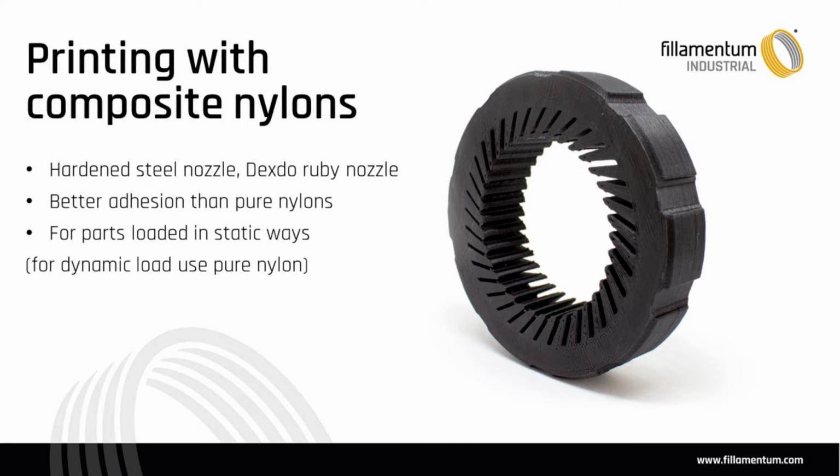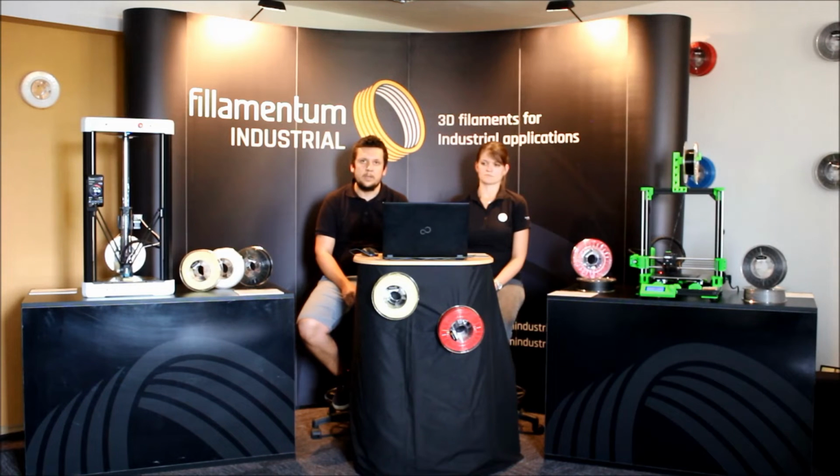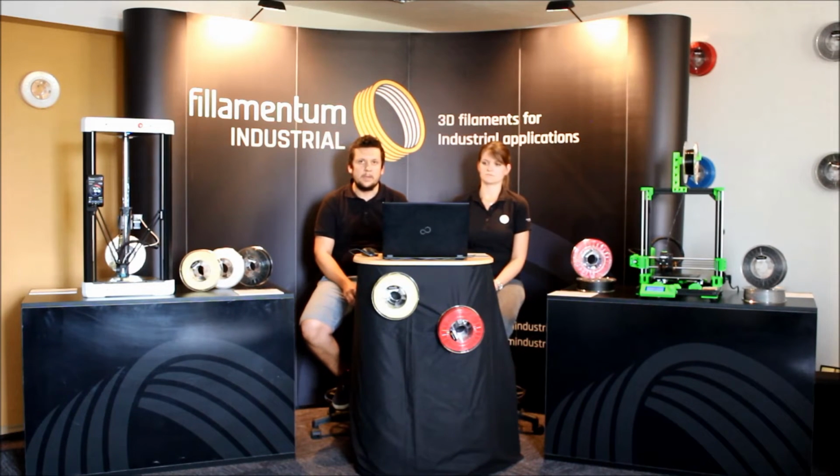And also, this is really important. The composite filaments are usually for parts which are loaded in a static way, like for hardness, pressure resistance, wear resistance, and so on. Because the carbon fibers or iron fibers are usually quite short, they don't give enough improvement in dynamic load.